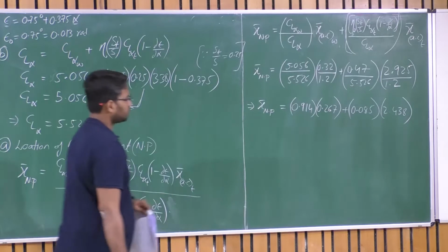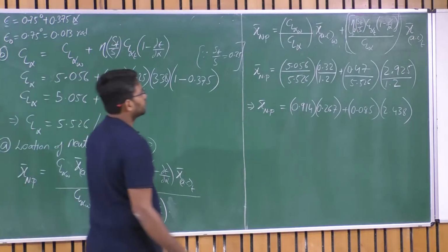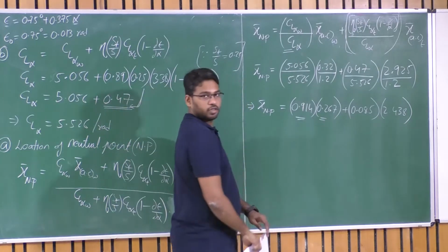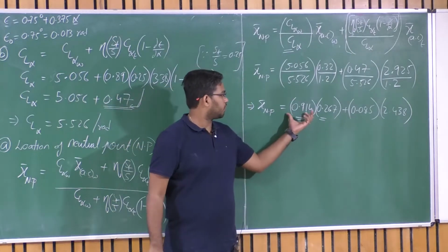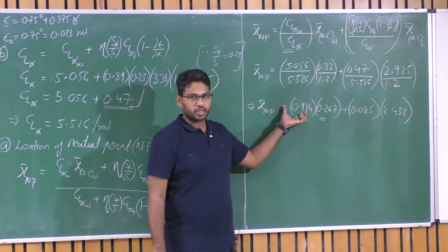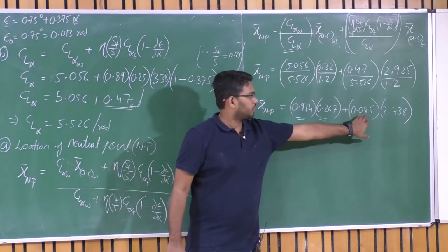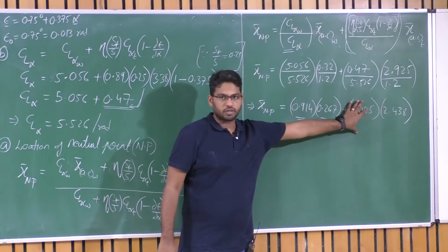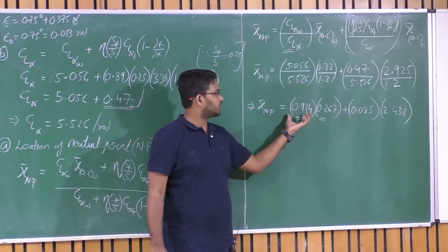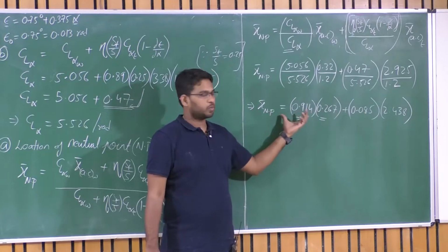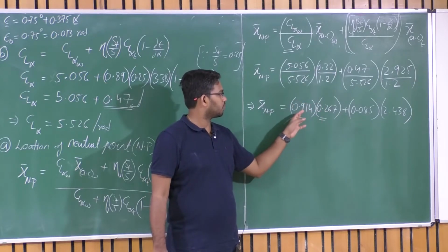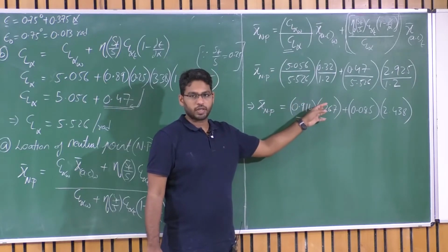So what do you mean by that? This ratio is the weight to the location, the ratio of the lift curve slope of the wing to the entire aircraft, and the lift curve slope of the tail to the entire aircraft. The wing has the major weight here, which is why x bar NP tries to have a major weight, almost 1, towards the wing aerodynamic center location.